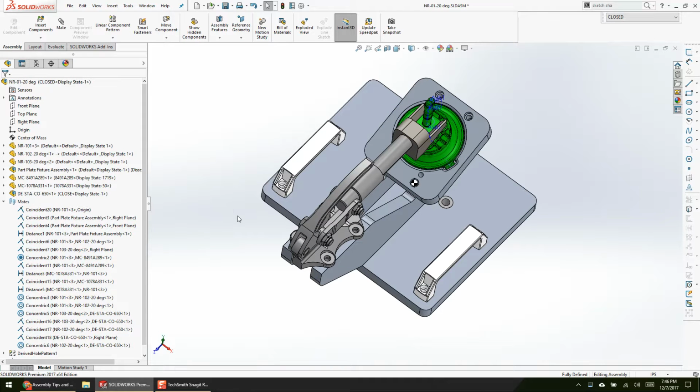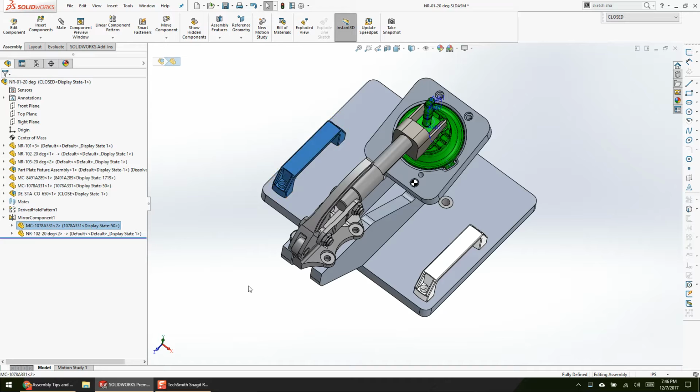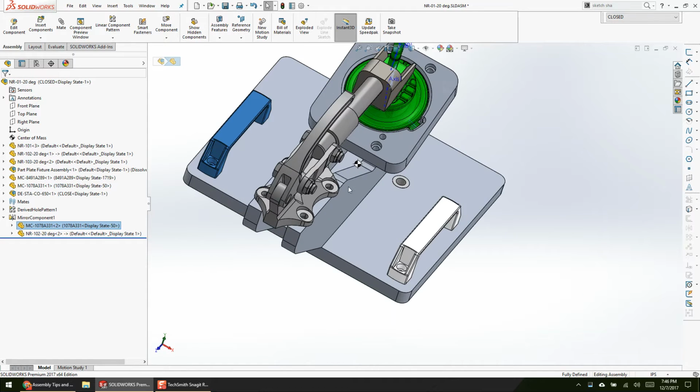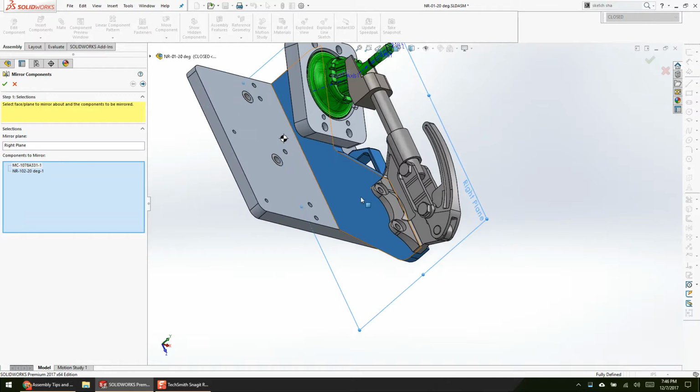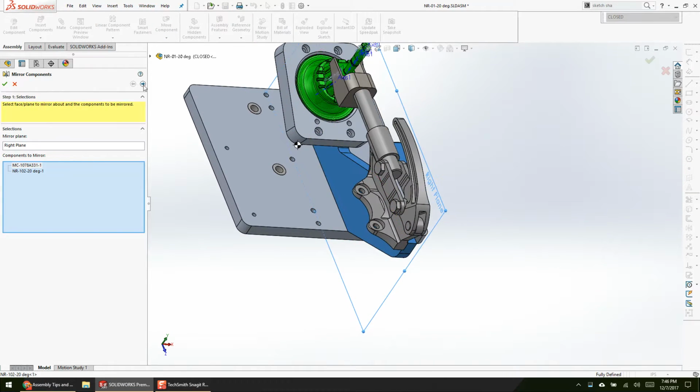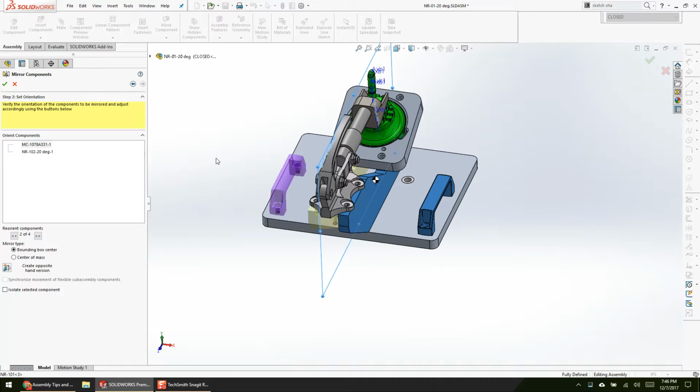So the other thing is here, there's no way that I was going to mate 2 handles in place. I have one handle, it's in its position, and I patterned that as well. I have the right plane down the center of my design because it's good design intent, right? This only works if the origin's in the middle of or where you logically want your part to be.